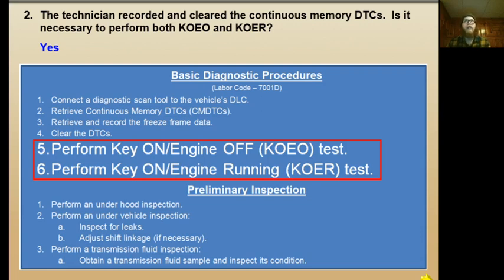So let's say we have a transmission fluid temp sensor that's setting a code. Now if the module sees that that temp sensor is showing negative 40 degrees and the intake air temperature sensor is showing 70 degrees, it does a correlation between those two and can realize that, okay, this doesn't make sense. So this is all done by the comprehensive component monitor that's part of our OBD2 check sheets when we do inspections, and it's for the emissions systems and government mandated P codes and all that kind of information.